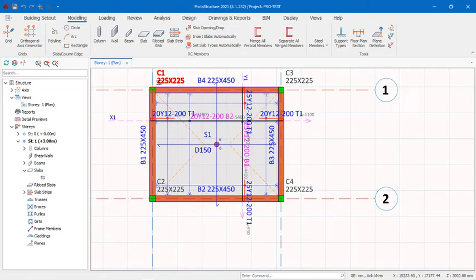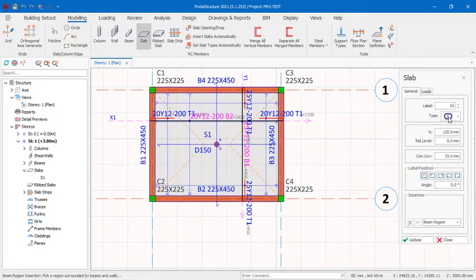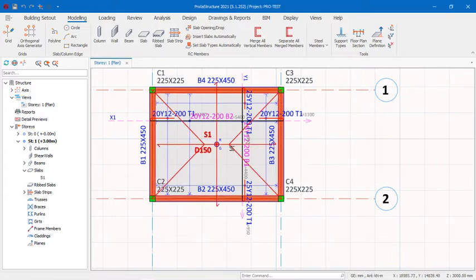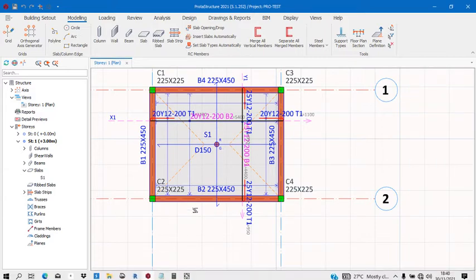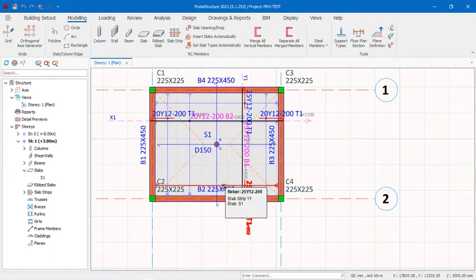Let's say I've inserted this column, this beam, and I'm putting this slab. Now, chances are that by the time I click this slab, you can see that it's showing me 1, which is case 1. Now, case 1 is different from case 9. If I click this slab and say it's inside here, and I run the design, by the time the software picks coefficient, the coefficient will be different.